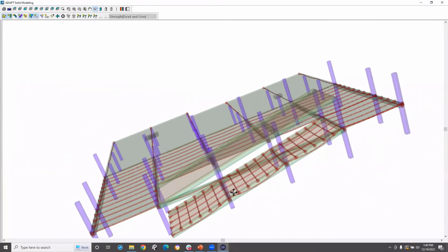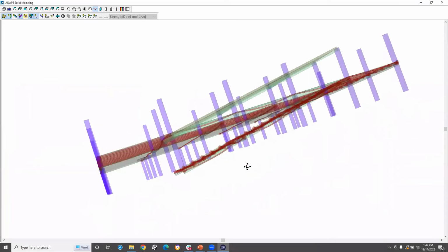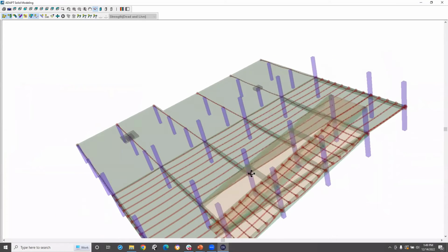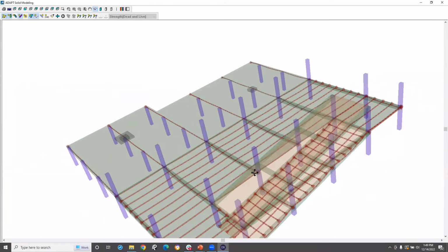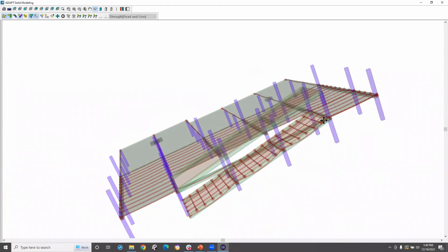I could, again, grab these and copy them up. I already have them on this ramp. You might be asking, well, why don't I see them? Well, we're in single level mode, right? And in single level mode, Builder only considers the one slab that we're on and the ramp below. If I wanted to consider the ramp above, I would then need to start looking at multi-level mode.